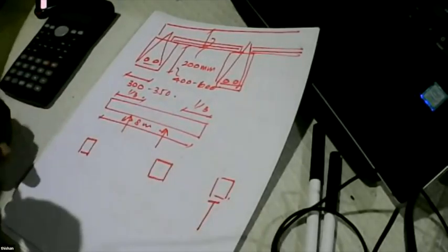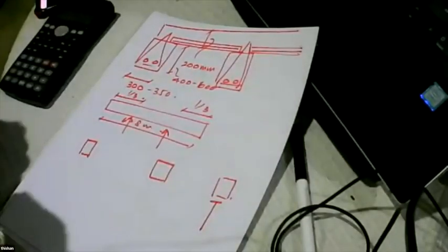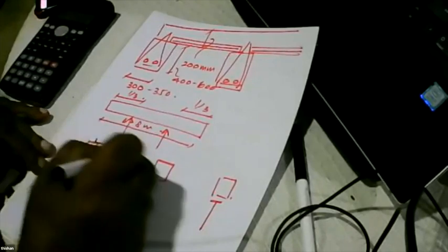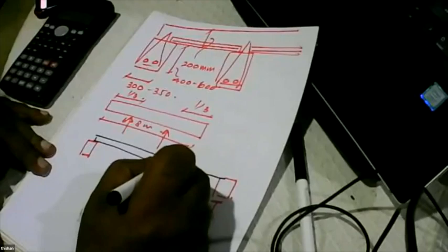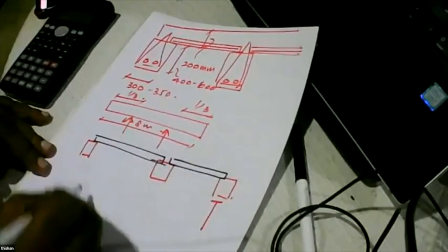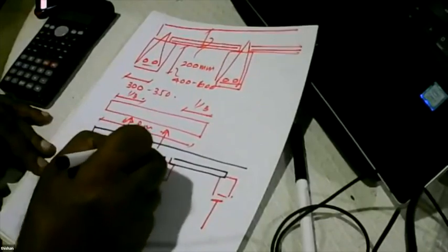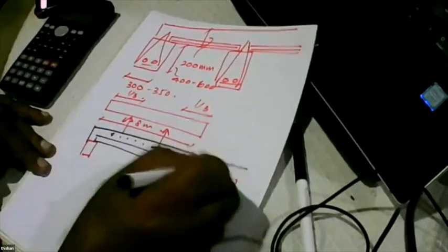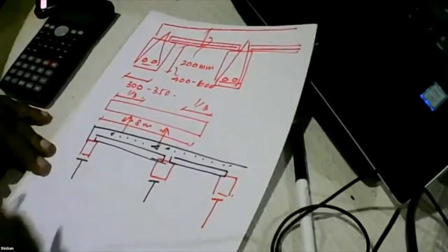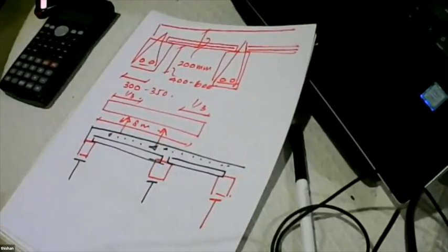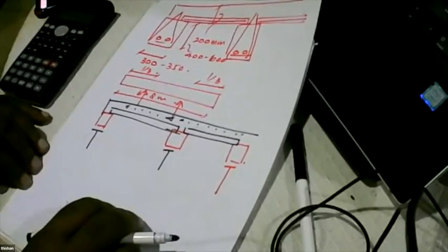When the self-weight is not a major problem, the moment you place the beams and place the slabs, this will become loaded. And then we are going to place concrete as well. So that's why I said it's good to have some support at 1/3 point.